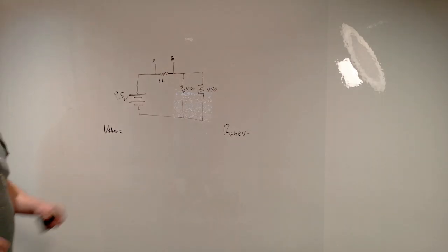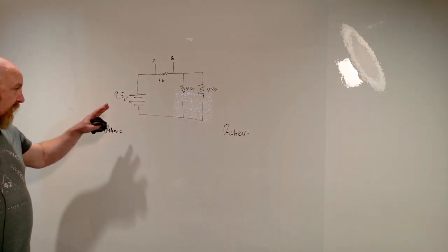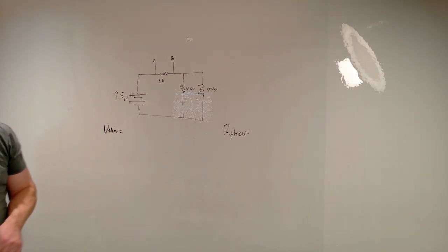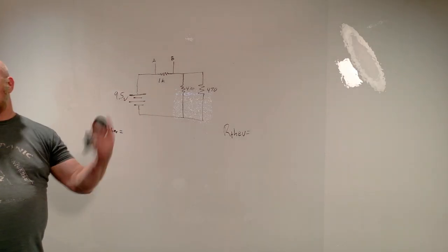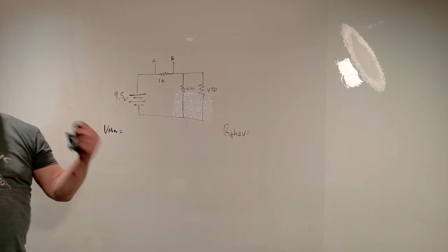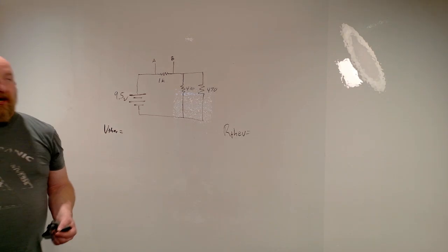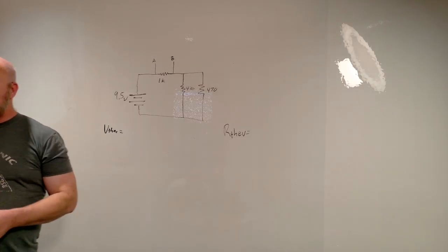Now, after we do some math here, we're going to figure out what our readings should be, and then we're going to check to see what we're actually getting on these. Let's keep in mind, we don't live in a perfect world. Tolerances. Wires have resistance. Our multimeter has an error range to it.